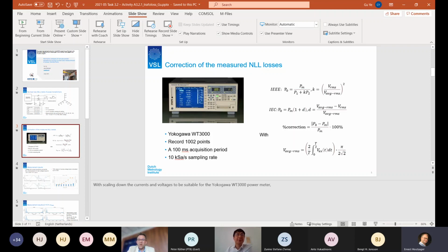So it was a high voltage generator with a relatively low output impedance. In that sense, I would be curious to repeat similar measurements with a less quality generator, if you might phrase it this way, otherwise say a generator with a higher output impedance. I would be curious what the results of the formulas on the harmonic power would be, and also whether the formulas would still agree that well.